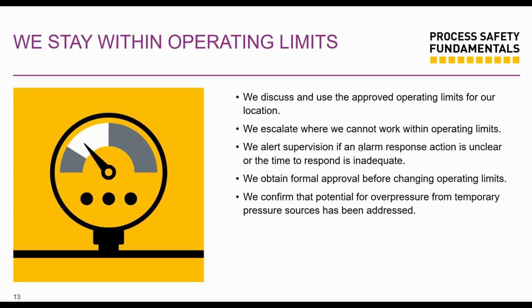So also we escalate where we cannot work within operating limits. Hey, this pump is pushing out too much, or we don't have a means to step down the pressure, and we can't work within operating limits. We should be worried. These alarms keep going off. This trip keeps tripping this pump. Why is that happening? So we need to have a clear response and clear response time, because a lot of things happen. This alarm goes, and within a minute after the alarm goes, we have a catastrophic event.